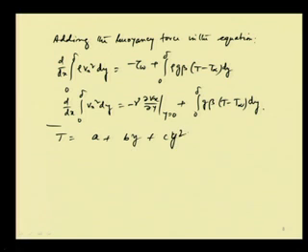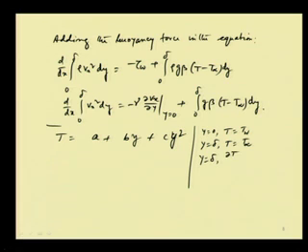Now, the boundary conditions are, at y equal to 0, T equals Tw, that is the wall temperature. At y equals delta, T equals T infinity, the surrounding fluid temperature, and at y equal to delta, del T by del y would be equal to 0. Once we reach the boundary layer edge, the temperature differences won't exist, they will be negligible.